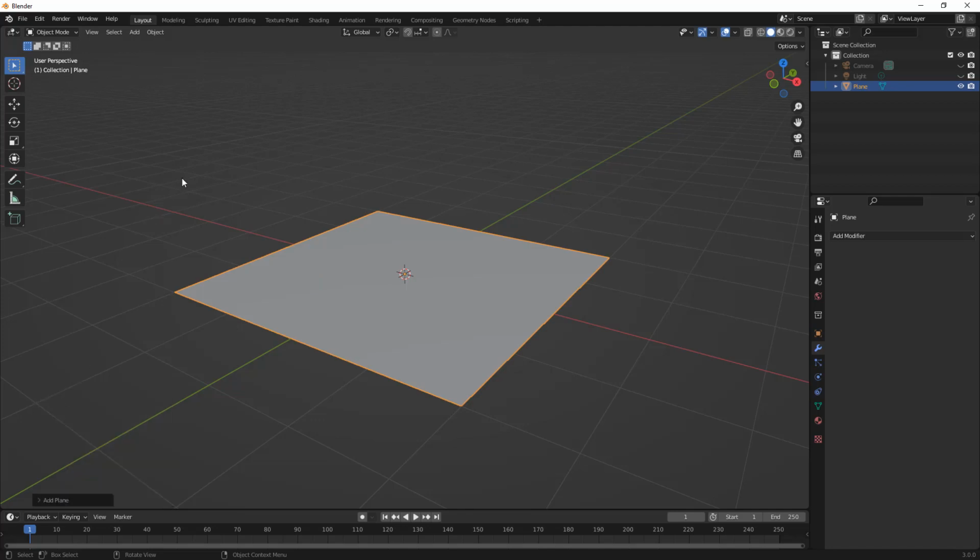We can minimize this add plane, and then when we left click inside of the grid system anywhere else, you can see that that option goes away. When we click on it, it's not there anymore, and that's because it was part of the add plane dialog box. Very similar to when we create a primitive in Fusion 360, as soon as we OK that dialog, it is completely gone. We can't get back to it.